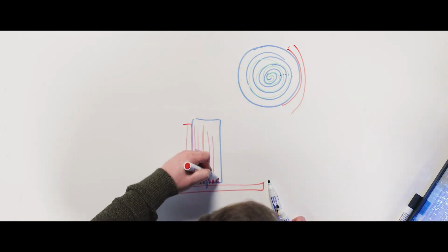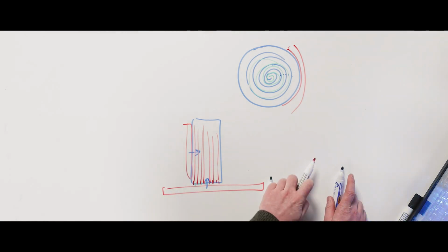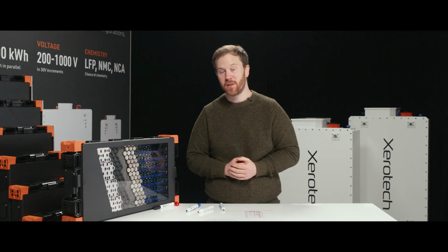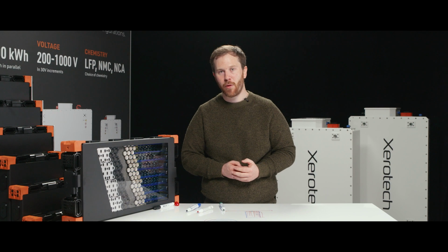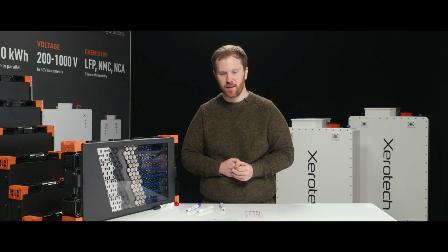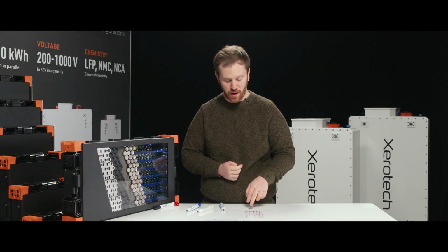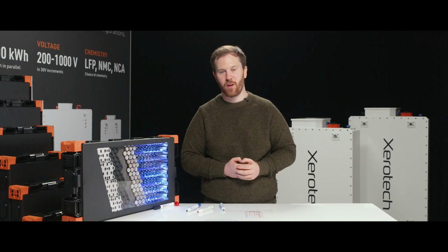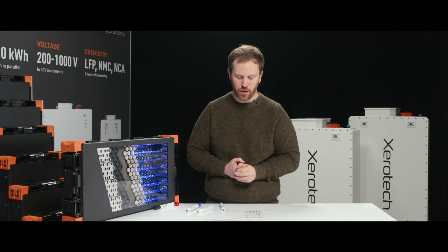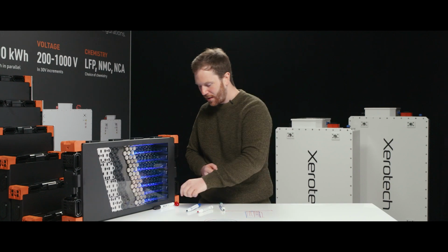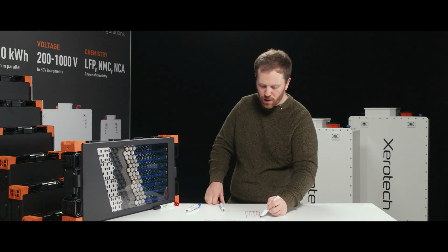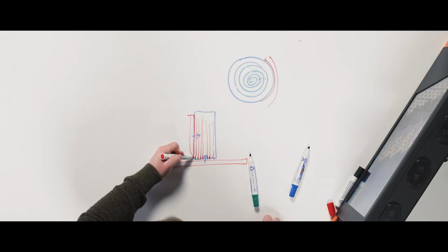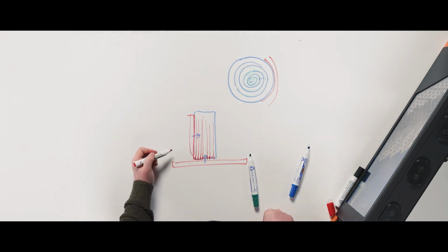There is some logic and rationale to that, but in all real applications, and from my own personal perspective, any high performance battery system I've ever seen across all suppliers, it's usually either a combination of cold plate and sidewall cooling or exclusively sidewall cooling, because you have to remember that in practical situations, cooling the sidewall, it also conducts down and cools the base of the can as well.